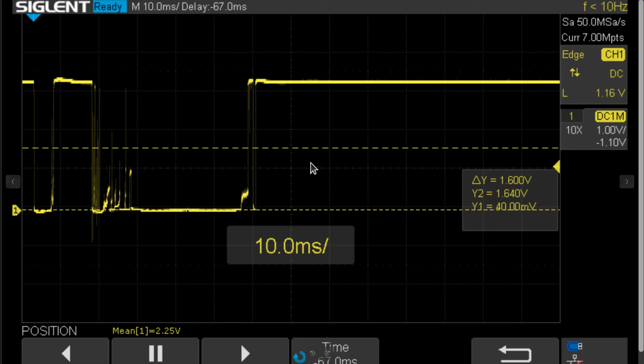Now, it depends on your needs, right? You may not want that, but that's why you have all these different types of debouncing circuits. For a human button press type of thing, this is a very common style. You see it change, make sure it stays stable for a little while before you say, okay, it looks good to me. I'll now proceed, propagate that signal to the rest of my circuit.